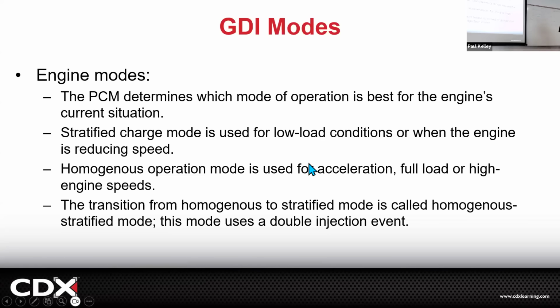And then we can even transition. We can go between the two, depending on the acceleration demands, but it's always trying to get the best emissions and the best fuel economy while still giving you the most power. This system's very advanced. Port fuel injection, not so much. They're just like, hey, let's try to hit about 14.7. We'll be a little rich, we'll be a little lean, we'll be a little rich, we'll be a little lean. This thing's like, no, we want 13.2. Boom, there it is. We want 14.7. The other crazy thing, this can do a lean burn where it'll do like a 15.7 rather than a 14.7. When you run it lean, you get really good fuel economy. It can do intense stuff on the fly.